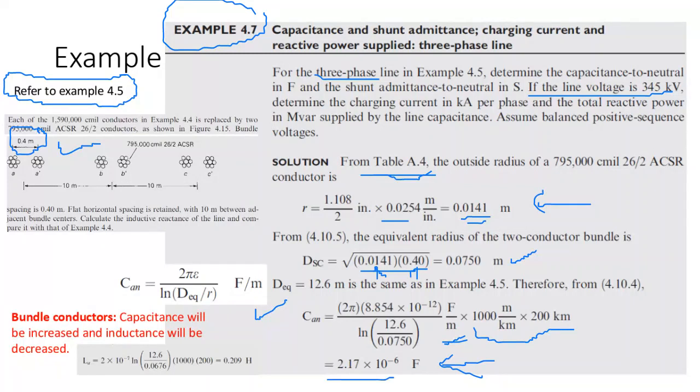You see now in farad, it's 10 to the power of minus 6. Farad is a very large unit, so it's not 2.17 farad. So please, when you write this, check that it makes sense. When you write numbers in any course, ask does this number make sense or not? If you write 2.17, this is too much. You cannot say that you forgot to write the power, because it does not make sense. So 2.17 times 10 to the minus 6, this is microfarad. 2.17 microfarad.